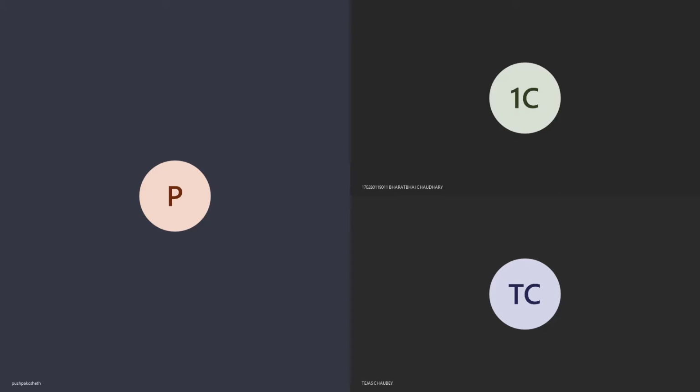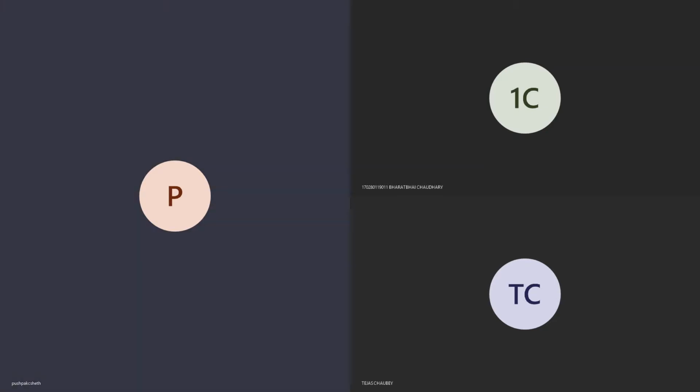That steam is passed through the turbine and expanded, and the turbine rotates, so that pressure energy and kinetic energy are converted into mechanical work, right? That steam is exhausted to the condenser, where it is condensed and converted back into water, so that we can feed it again into the boiler through the feed pump, right? So that is the